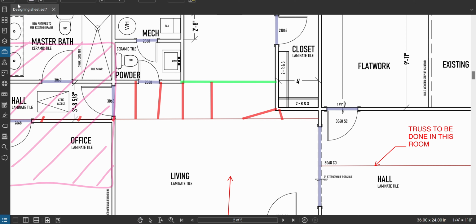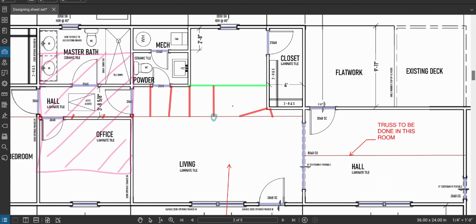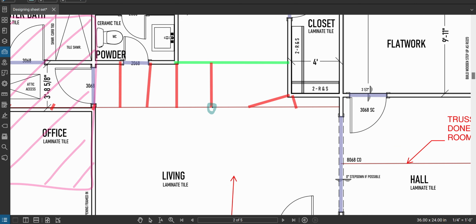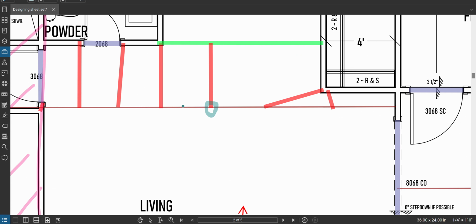So the first thing is, what is the center of the support on the roof ridge? It's right there, right? So this little spot right here, that's what I'm concerned with. I'm not concerned with where I'm holding it up on the beam. I'm concerned with the ridge. This is where all the loads are being taken to on the roof, and then that load's going to go down through the roof brace to the beam. So I'm concerned with this point here. So I'm going to play the halfway game. On this roof ridge board, I have a support here, here, and here.